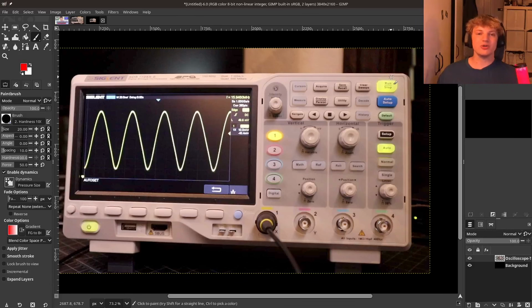So of course, we're going to need an analog to digital converter. This is going to make up the core of our oscilloscope function. These are all really useful and really important things that our project might want. And you can sort of see the process I'm going through here, where I'm taking the abstract idea of an oscilloscope and breaking it down into components we can add to our design that will actually make the functionality happen.